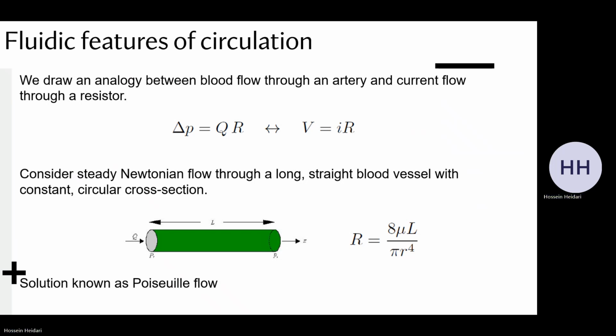So the key thing here is that delta P, Q relationship has a coefficient, a correlation factor R, which is defined with this equation, which has to do with this parameter, the viscosity of the fluid that's carrying through. And as it becomes more and more viscous, you can imagine that the resistance is going to increase, right?